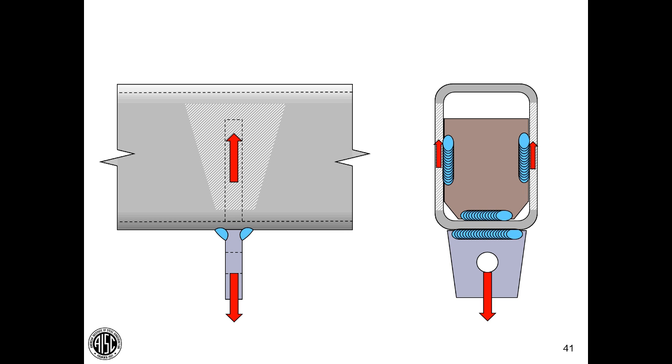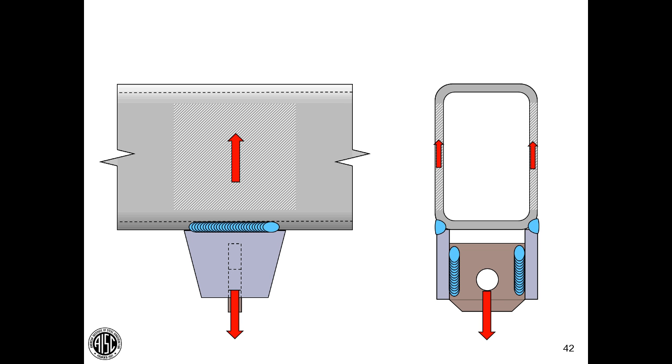Another alternative, one that does not require welding inside the tube, would be to build a bracket up on the outside of the tube. Now the vertical load goes through the brown member, through the fillet welds, into the purple, and directly into the member that lies parallel. And we have a very effective load path. It's predictable, and we have evenly loaded welds along their length.